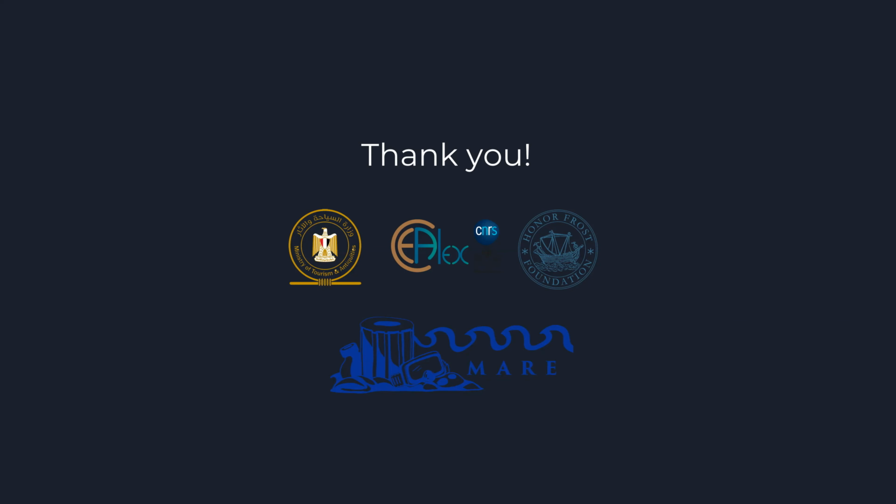Okay, we got another question from Sarah. Do you need to take the photo twice or multiple times? You showed us one picture where the blocks are visible, and after a couple of years they are buried under sand. Yes. As I mentioned in the first lecture, when we take photographs for each season or each year, we have to make sure there is an overlapping area between one season and another, so that when we georeference the 3D model, it's accurate enough.